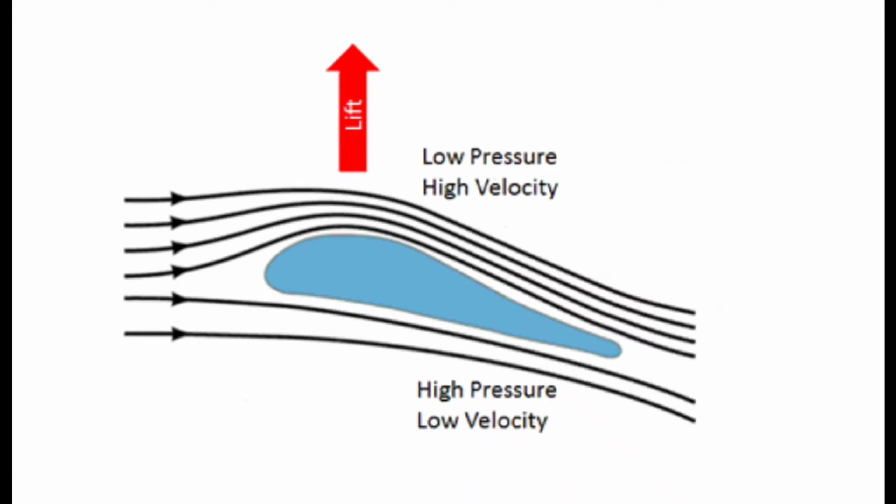During flight, air naturally flows over and beneath the wing and is deflected upwards over the top surface and downwards beneath the lower surface. Any difference in deflection causes a difference in pressure, and because of the airfoil shape, the pressure of the deflected air is lower above the airfoil than below it. As a result, the wing is pushed upwards by the higher pressure beneath, or you can argue it's sucked upwards by the lower pressure above.